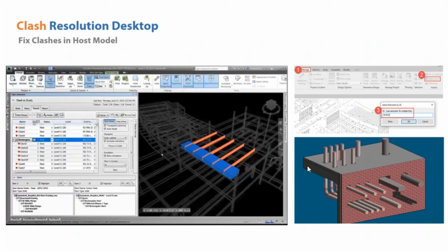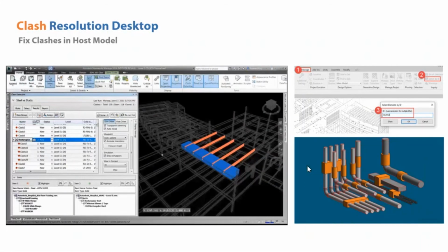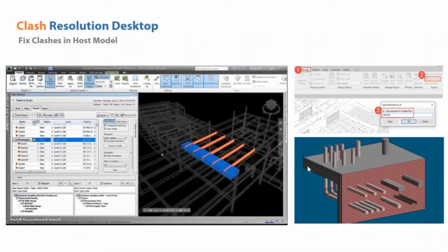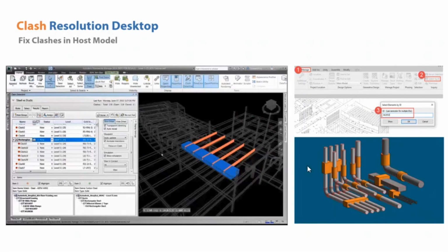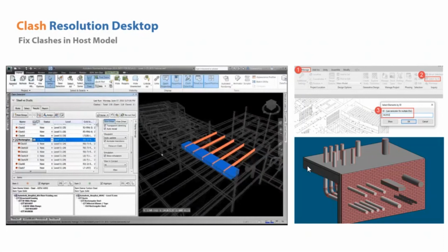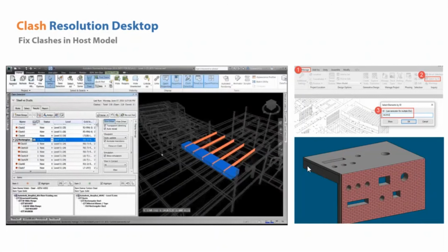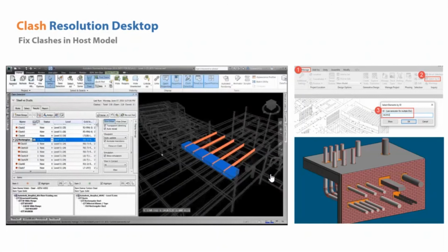Like AGA CAD, they have a specific module for the creation of cut openings which will identify the clashes between piping or ducting elements and structural elements like floors or walls. Then it will automatically create the void space which is required for the smooth transition of the particular model elements in a very short time period, which can save considerable time in the modeling aspect.